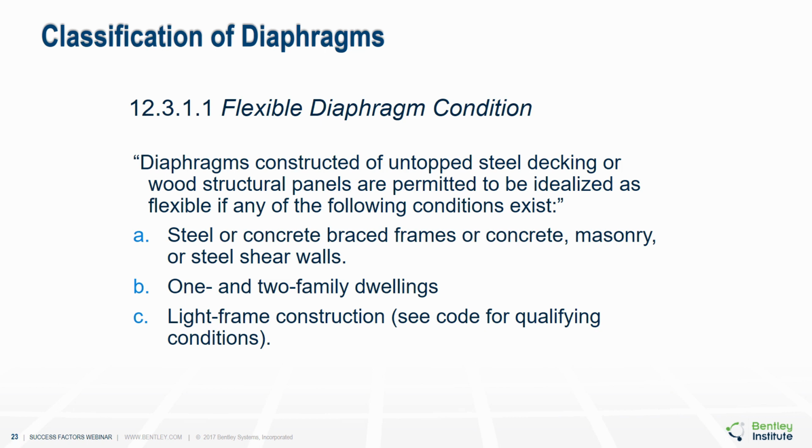Also note that the code says any diaphragm is permitted to be idealized as flexible. Any diaphragm is permitted to be analyzed as a semi-rigid diaphragm. If you want to go to the effort to model and analyze as a semi-rigid diaphragm, you're free to do that regardless of what other sections of the code here indicate for flexible versus rigid.